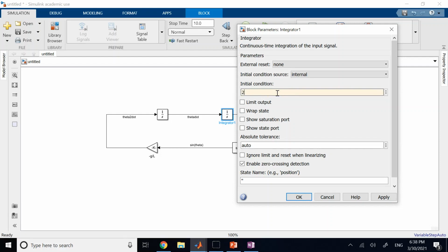So if it's like 2 times 5 divided by 3.6 and then raise the whole thing to the power 3, you can just leave it like this. You do not need to simplify it first, get it into one single decimal and then paste it here. So in this case, you simply say pi over 4. MATLAB will calculate that.